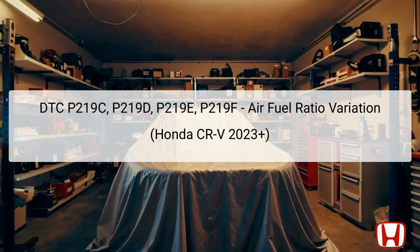P219F for cylinder 4. When these codes are triggered, it indicates that the Powertrain Control Module (PCM) has detected an abnormal fuel coefficient in these cylinders, suggesting that they are not operating efficiently. The PCM continuously monitors these ratios and compares them to specified ranges, logging an error if deviations occur.